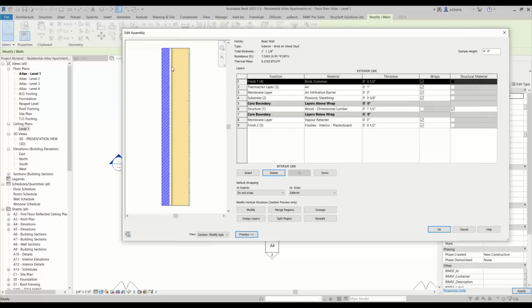Sometimes, if it encroaches into the structural space, or Revit considers it encroaching into the structural space, you might have your studs end super short and be right under the reveal or right under the sweep. So just keep that in mind. If you do have any reveals or sweeps, just do a few tests and see if your panels are creating properly. Add a window in there, check if it's creating properly. If everything is working great, no need to change it. But if it is not, then please do make sure that you change it.